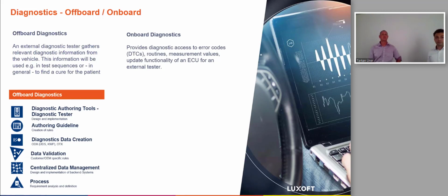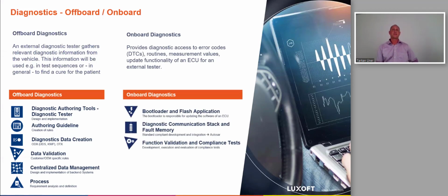All right, let's go to the next topic, onboard diagnostics. So previously, Tarkan said offboard diagnostics is everything related to diagnostics outside the vehicle. Well, onboard diagnostics is everything related to diagnostics within the vehicle. So on a high level, all ECUs that a diagnostic tester can talk to and which provide a diagnostic interface for reading diagnostic relevant information, controlling actuators from within a diagnostic tester, writing values into an ECU, and so on. Furthermore, all logic inside an ECU, monitoring the input and output pins, controlling them, evaluate and store a DTC within the fault memory, providing functionalities to update the ECU software.